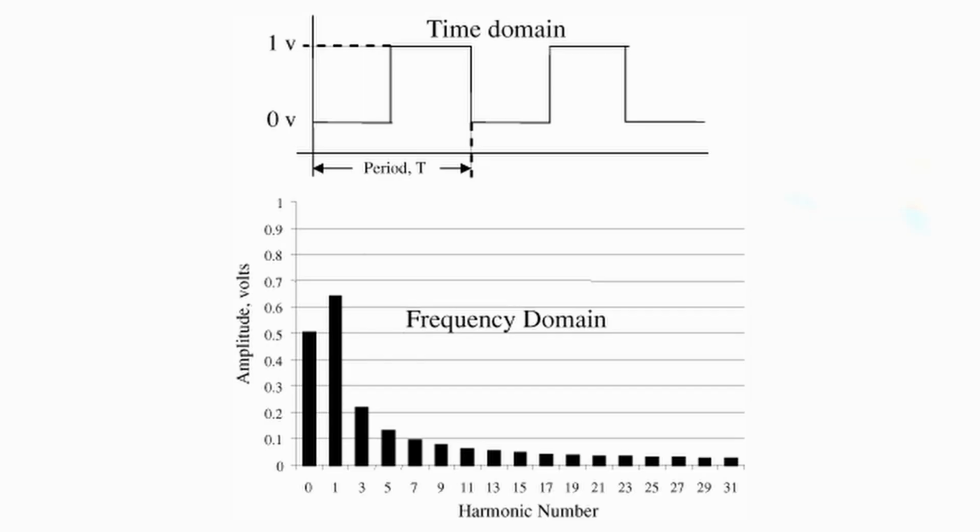So bringing us back towards the EMI problem, what it all boils down to is that the magnitude of the harmonics of those square waves will decrease linearly as the frequency increases. So you would think that our radiated emissions would also decrease, right? Well, that's not the case, because if you remember, there is a quadratic relationship between the frequency of the signal and the strength of the magnetic field that it generates. So that actually will overpower the decreasing current amplitudes and result in actually higher overall emissions, which sounds pretty bad for us, except for one saving grace.